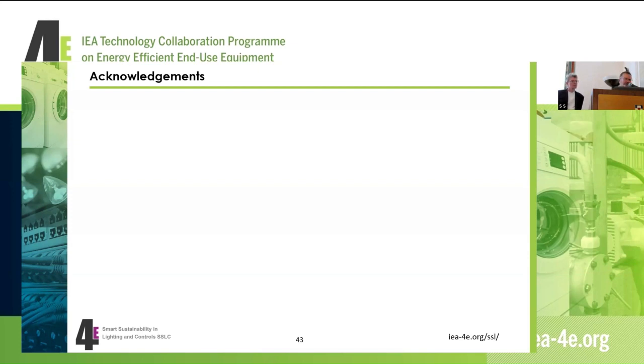There's a limit of utilising the formula in the test method to lumen maintenance maximum of 96%. And so you're getting to the point where we need to have a better understanding of the uncertainties of measurement and the repeatability of measurement of laboratories to be able to improve that, so we can get a more precise determination of what that lumen maintenance is for those projections.